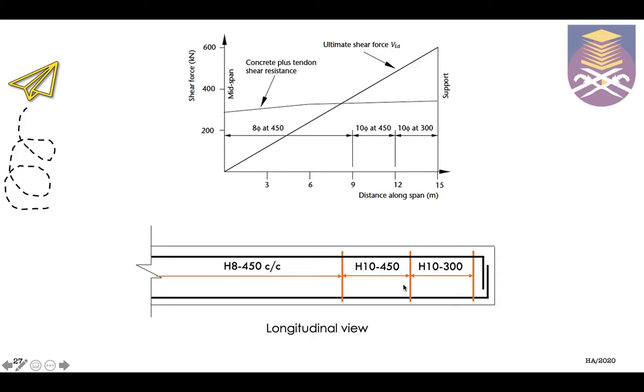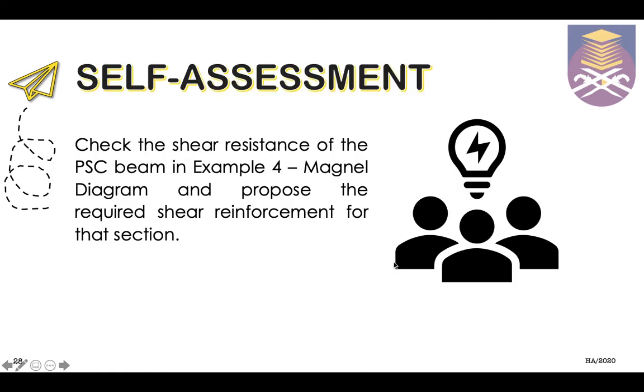Then towards the midspan, the shear reinforcement is reduced to H10 450. You can see here that the spacing is further apart.